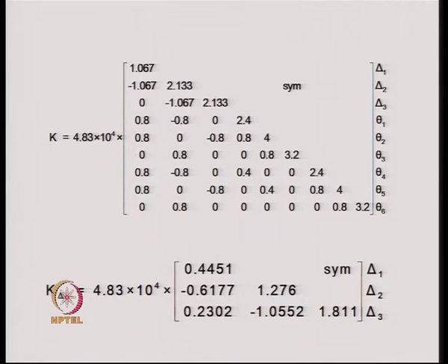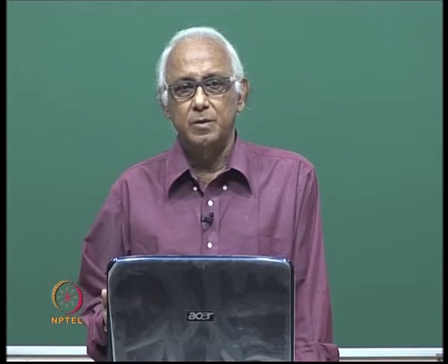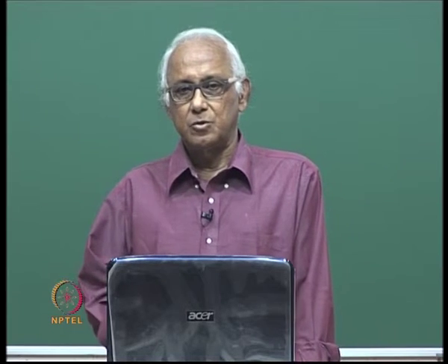So, this was the scheme for the calculation, and therefore, we see that at every instant of time t, we have to check in the beam members whether a plastic moment is there at a particular cross section, and if there is a plastic moment coming at a particular cross section, then we assume for the next analysis a simple hinge at that particular cross section, and carry out our solution with a modified stiffness matrix Kt.